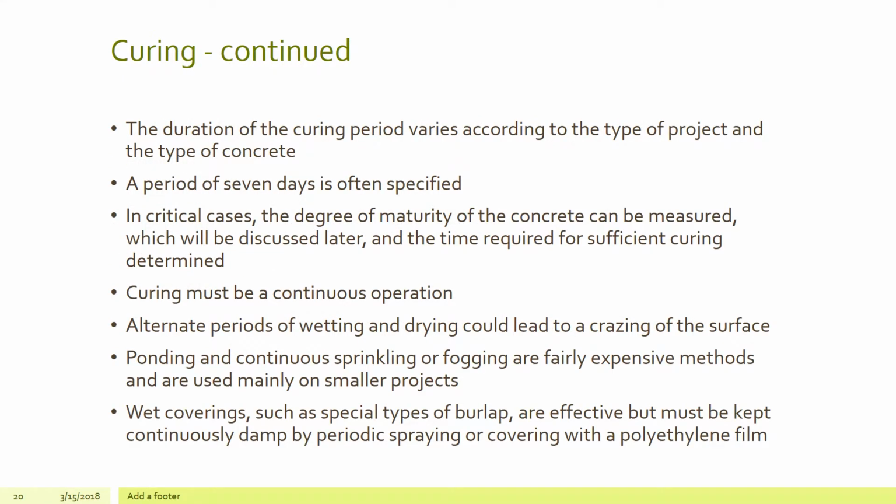The duration of the curing period varies according to the type of project and the type of concrete. And of course, we're also looking at environmental conditions. What's the sun? What's the temperature? Where is the sun? Is it cold? How's the wind blowing? There's a lot of factors that come into play there. A period of 7 days is often specified.